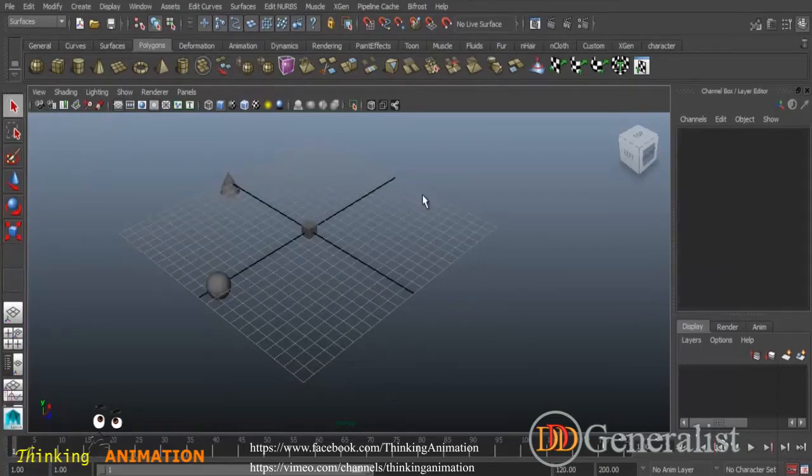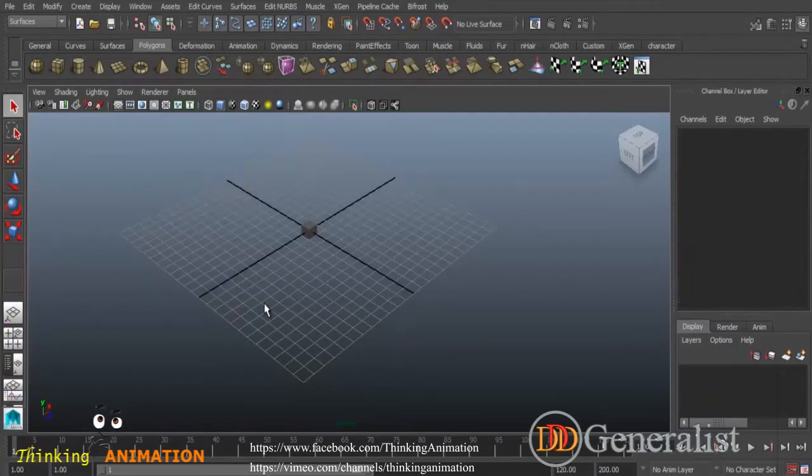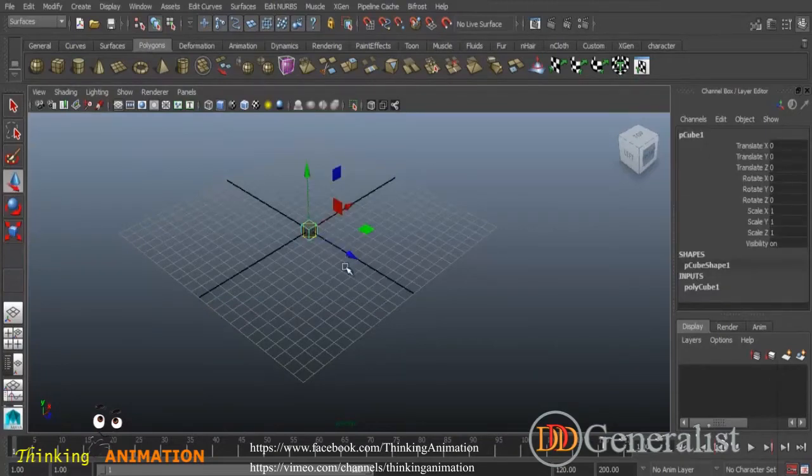Even you press your right mouse button, hold it and come to select all, and that way you can select all of your objects. But how can you move your objects around? How can you navigate your objects around? And if you select all of your objects and press the delete key from the keyboard, that way you can delete the objects. So here is a move tool. If you select the move tool, click your object. This way you can easily move your object around. You get the three axes right here: the z-axis, the x-axis, or even the y-axis.